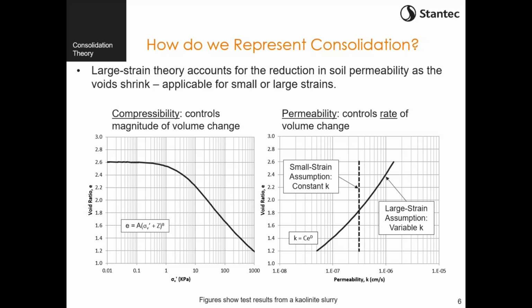So if you're familiar with an odometer test, with Terzaghi's consolidation calculations, things like that, these are the types of consolidation calculations that would be used for, let's say, settlement beneath a footing of a foundation or something along those lines. And for those types of calculations where the change in void ratio is relatively small, in other words, very small volumetric changes or strains, that assumption is valid.